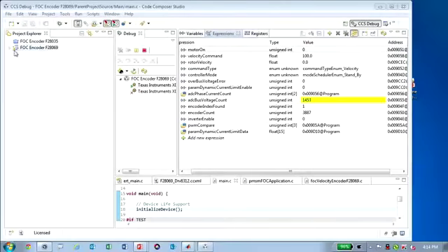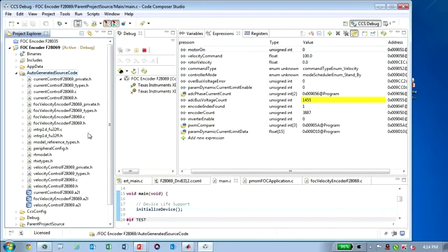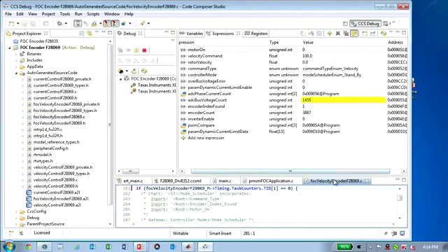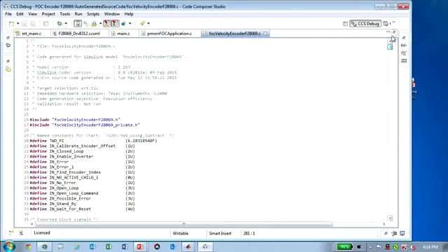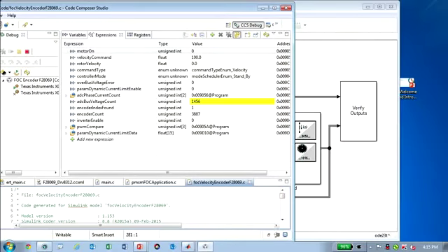In this environment over here, this is our handwritten project, but included in our handwritten project is code that was automatically generated from Embedded Coder. And if we take a look at this code that was generated from Embedded Coder, this code was generated Tuesday, May 12th, 1558, so it's fresh. Once we've generated that code, we call it from our interrupt service routine, just like you would call some other piece of hand code. And you can work with it in your embedded environment just like you'd work with other pieces of hand code. So for example, this is a watch window in Code Composer Studio.